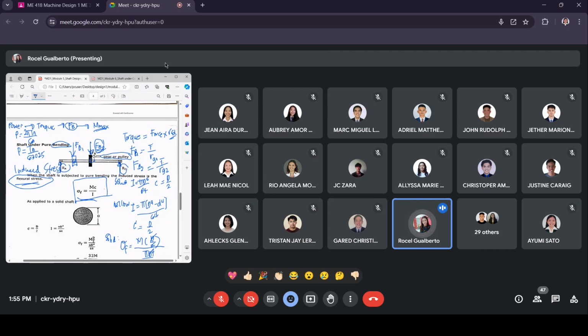In knowing the shear and moment diagram, it is necessary that you know these values RA and RC, and that can be determined using, of course, equations of equilibrium. You can take moments on any of these sides to obtain one unknown. So that is how we do it.